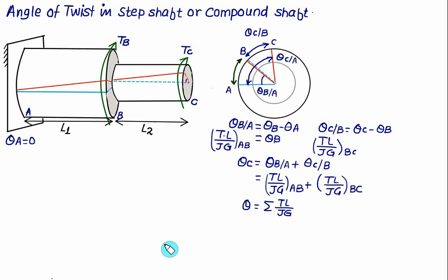The only question to be answered is what torque is acting on the shaft AB and the shaft BC. We can have two approaches here. The first approach is to draw the torque diagram and consider clockwise torque as positive and anti-clockwise as negative. You can take any sign convention you want, but you must stick to it throughout the multiple torques. Always start the diagram from the free end and close it at the fixed end. You start at 0 and end at 0, and then the torque diagram will be complete.